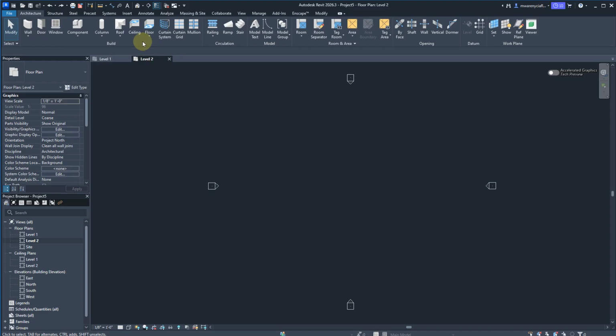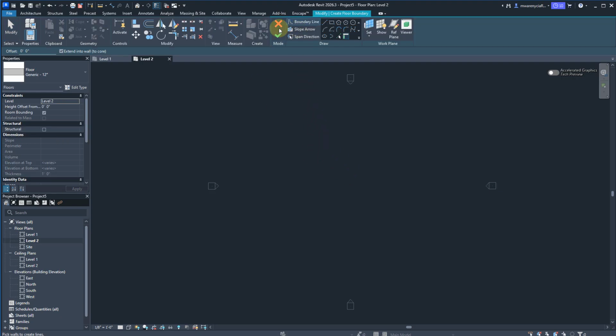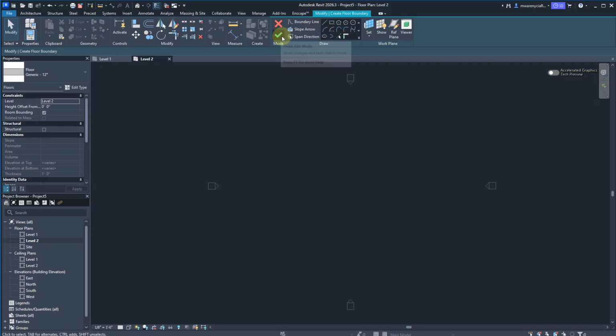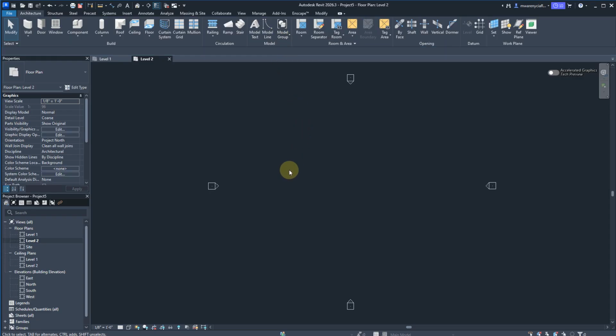There's another type of modify panel that you'll run into, or at least an analogous system. For things like when we're placing floors, you can see that instead of what I had before, there's now a green check mark and a red X here. And if I hit escape, nothing happens. I'm kind of stuck in here. And you can tell it's in that state because if I go back here to architecture, these are all grayed out. So if you want to get out of that, either finish what you were doing or click the red X just to get out and it reverts to whatever it was before.